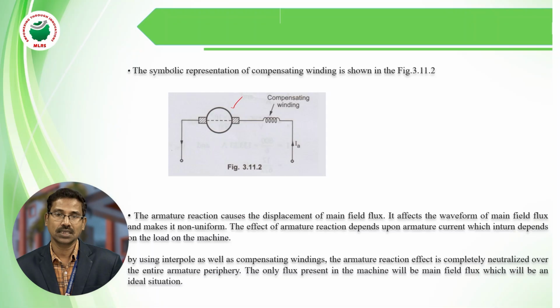Under that condition, the armature flux gets neutralized. The sparking that takes place at the brushes will be minimized, and the commutation problem will be reduced. By that, the commutation can be improved.